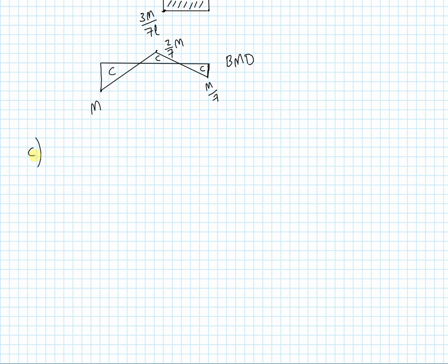And next up, we're going to do the reaction forces. The reaction forces are really simple because they simply correspond to the values that we see with the bending moment, with the shear force diagram. And that's what I'd like to highlight now. So let me draw a pin support, a roller support, and a fixed support here as prescribed by the question. And now I'm going to draw my reaction forces.